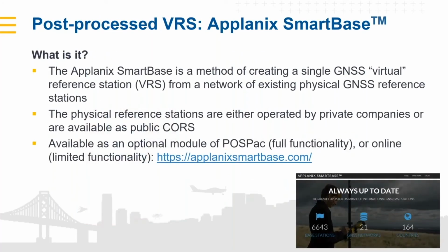Talking next about a VRS, which is trying to eliminate some of the limitations that are found with single base processing. There are two Applanix SmartBase options that I'm going to talk about real quick. There is a full version, through POSPac, which has functionality for creating a rover, or virtual reference station, that moves with the rover, trying to minimize that baseline length, as opposed to an online version.